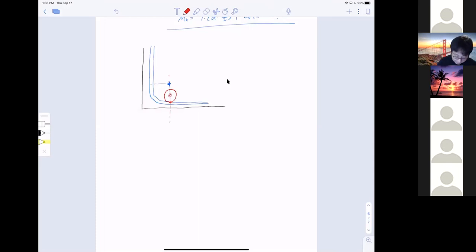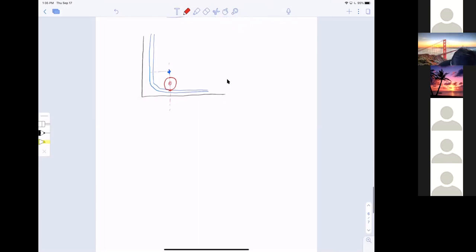Now, the distance between the edge of the stirrup to the center of the bending radius is 2ds, with ds being the diameter of the stirrup. Then the distance from the edge of the bar to the edge of the stirrup would be 2ds minus the diameter of the bar over 2, I believe. Yeah, so this is the so-called gap. That's where the confusion is, I think. And that's constant throughout, even though the figure in the homework kind of looks like the bar is touching the stirrup on the left side.